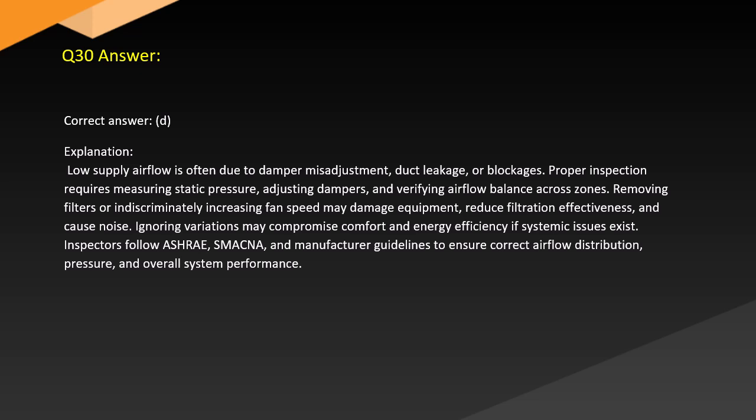Removing filters or indiscriminately increasing fan speed may damage equipment, reduce filtration effectiveness, and cause noise. Ignoring variations may compromise comfort and energy efficiency if systemic issues exist. Inspectors follow ASHRAE, SMACNA, and manufacturer guidelines to ensure correct airflow distribution, pressure, and overall system performance.